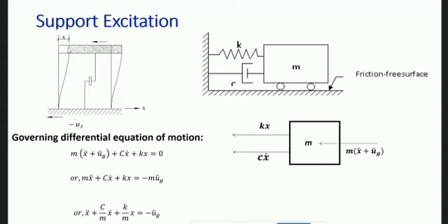So there is some kind of energy dissipation or energy absorption, and that also adds to the damping effect. So the total damping is expressed as a viscous damping. That means the damping which is proportional to the velocity, which we have already talked about. And this is denoted by this damper, okay, the total damping which is acting.